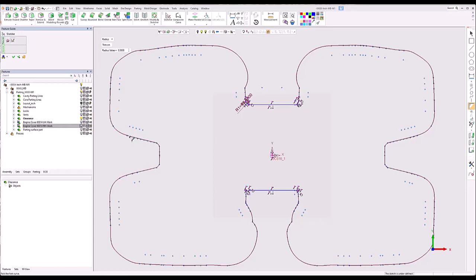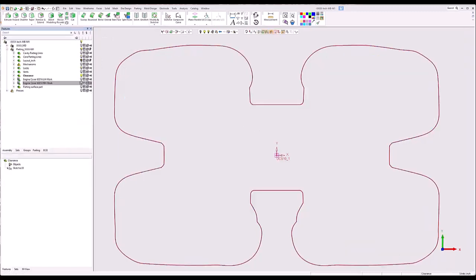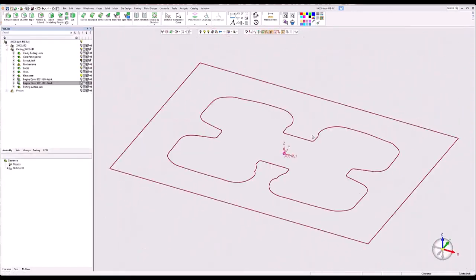All these little points here and that, I could get rid of all these little segments and make one curve. Sometimes I will go around and clean up this geometry. What ends up happening when I extrude it, it's going to make little slivers, and we can take a look at those in a minute. It's usually the biggest cause of extend object offset. Like I said, we'll take a look in a minute at where that affects you.